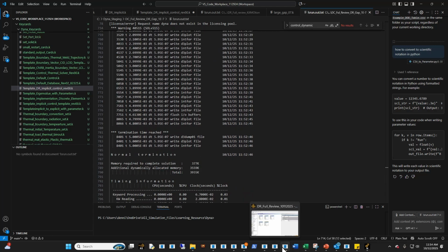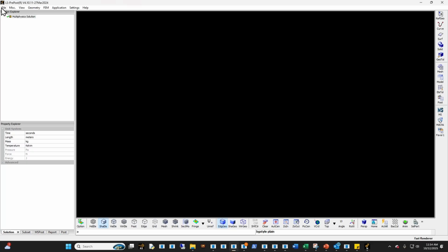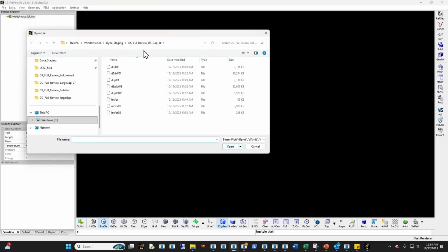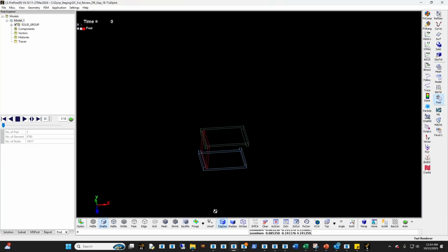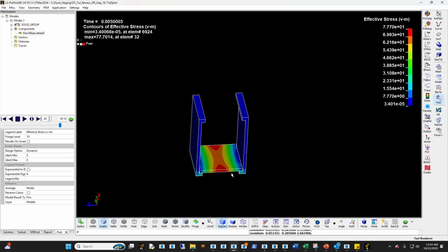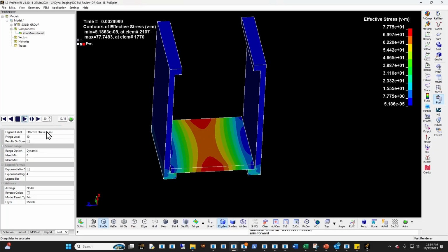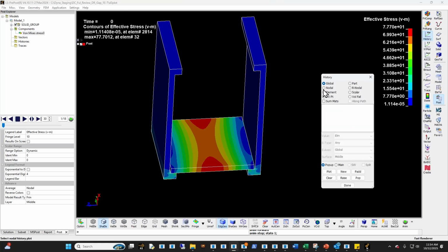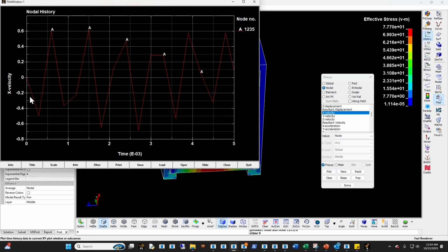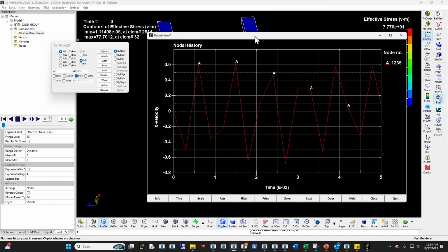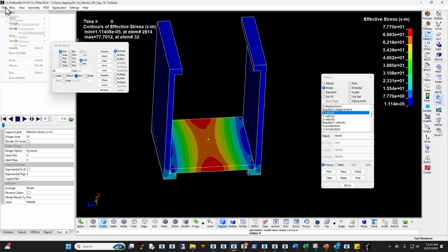And then once you have that, what we can do is look into all those parameters and do some post processing, right? So let's do this one. Let's do D3plot. So this is with 1e-7 dynamic relaxation. You can see in this case, if I were to probe the stress, the ringing will be much lower. You see there's almost no ringing left. And then what you do here is you do nodal and do y velocity, x velocity. And you can see this is a very, very low curve, right?